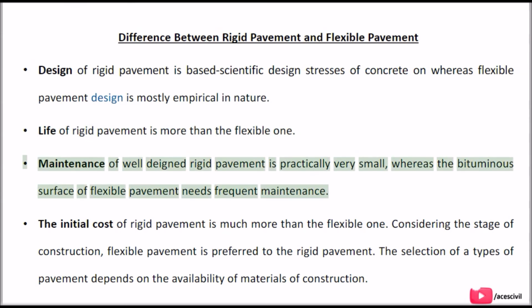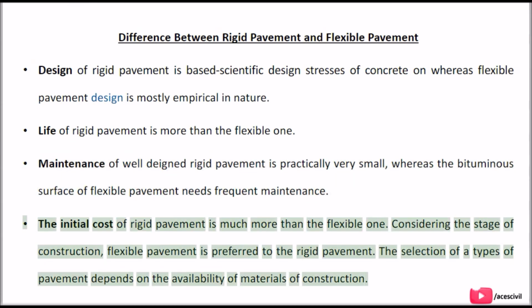Maintenance of well-drained rigid pavement is practically very small, whereas the bituminous surface of flexible pavement needs frequent maintenance. The initial cost of rigid pavement is much more than the flexible one. Considering the stage of construction, flexible pavement is preferred to the rigid pavement.